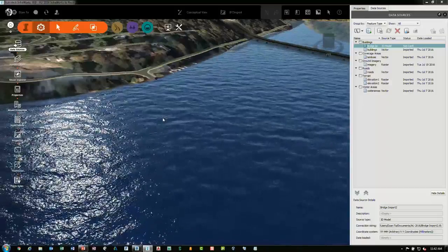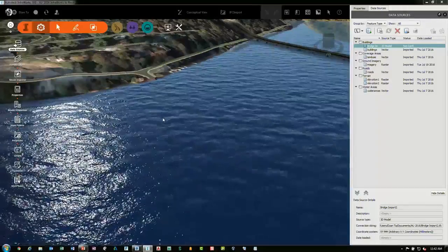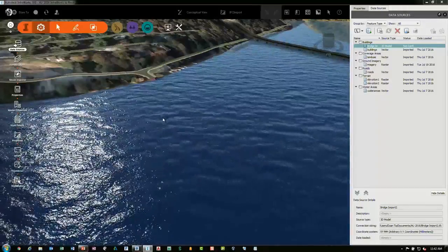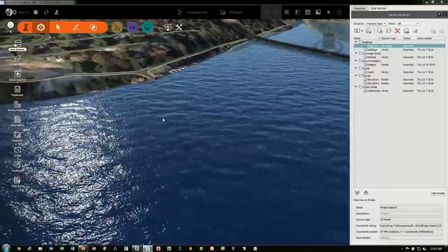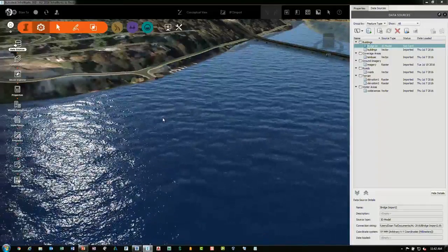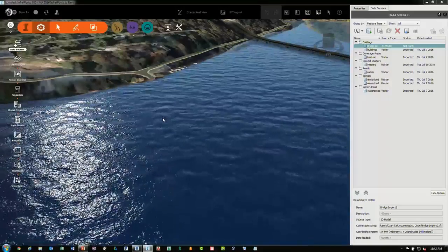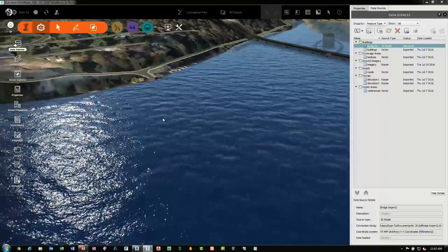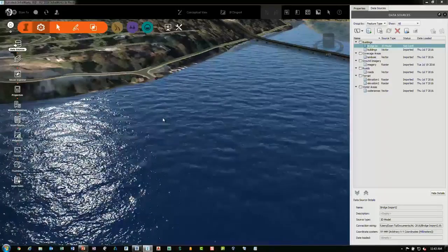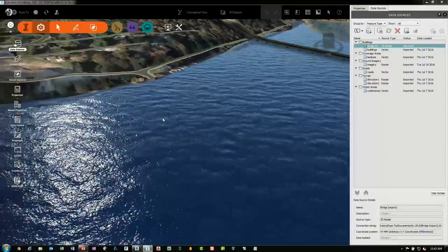And depending on the software that you're working with, some software accepts IFC files much better. For example, Navisworks accepts IFC files very well. Taking an IFC file and bringing it into Revit is a 50-50 shot, okay? And it's just very, very strange with the IFC file format.